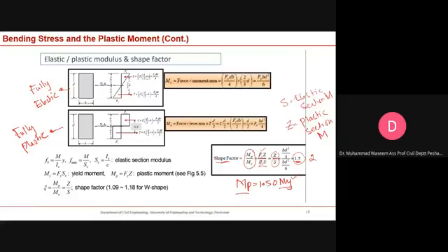The moment arm you can calculate, this is about 2 D by 3, if I remember. So you just add them together and you will get this moment arm. Once you have this force and this moment arm, but please remember this force and this force are both equal, you multiply the force with the moment arm, and you will get a certain magnitude of the yield moment in the elastic state. What will be the yield capacity of this cross section? So you can come up with this formulation.